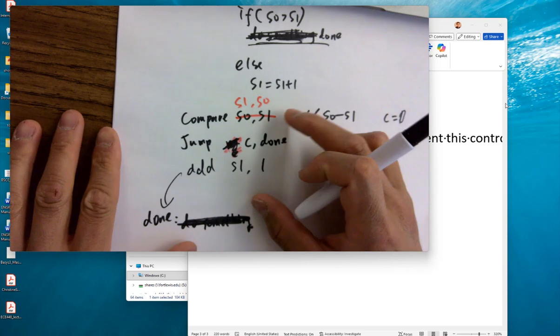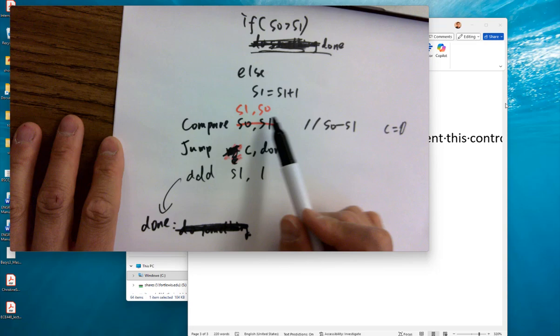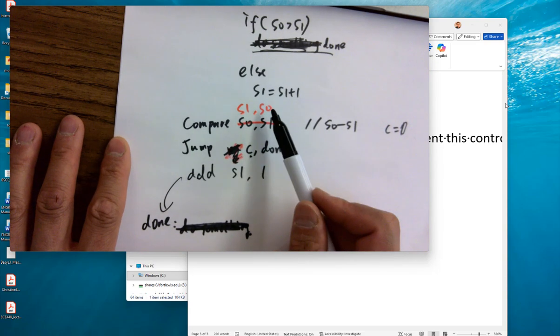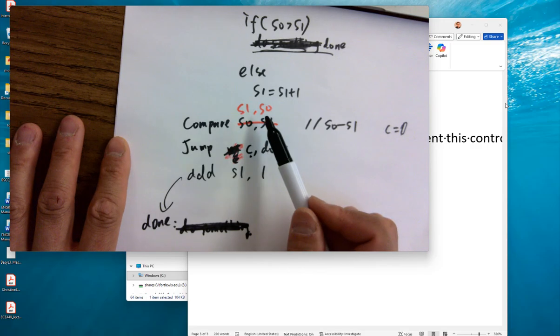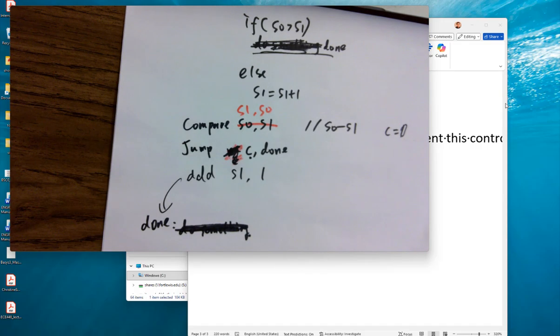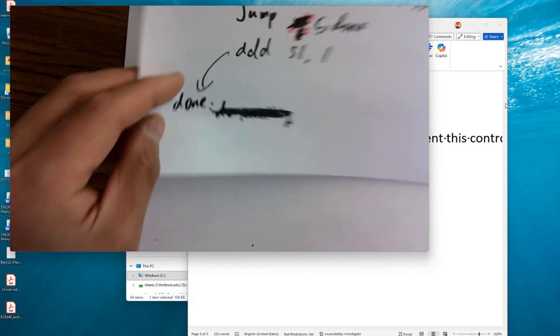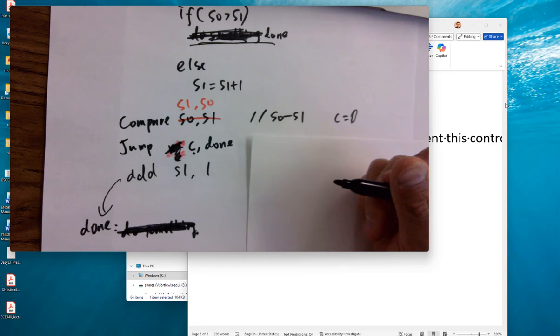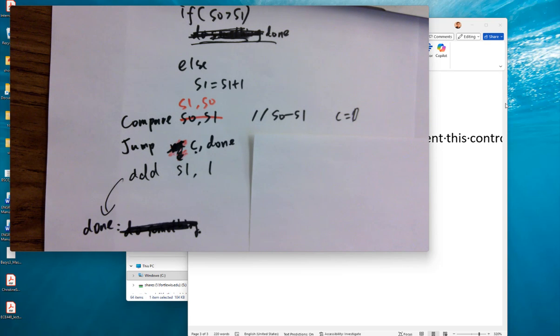You see the difference here, right? Because this is gonna give you a definitive answer, so you can use jump C. If you do S0, S1, then you don't know which one to use. Jump C or jump NC wouldn't work, right? Would it work at all? Should we try it? If we do like adding Z to it, that's too many conditions. Unnecessary, right? Because this is very simple.